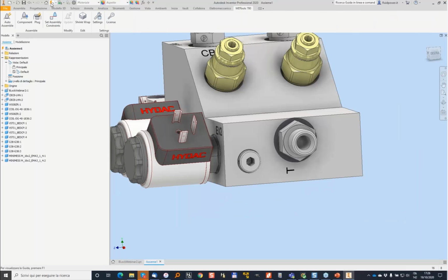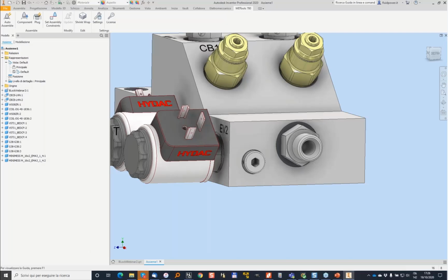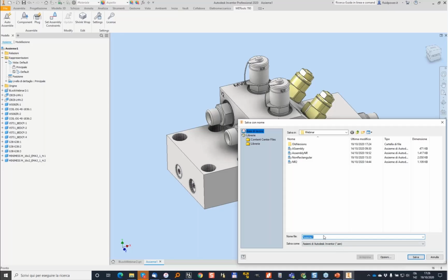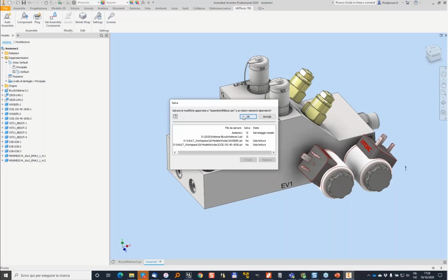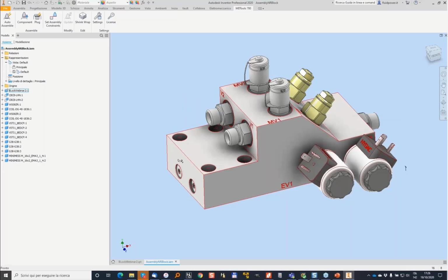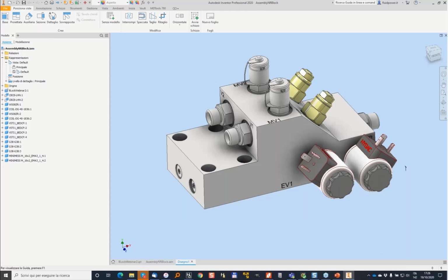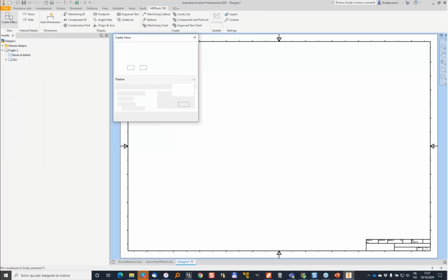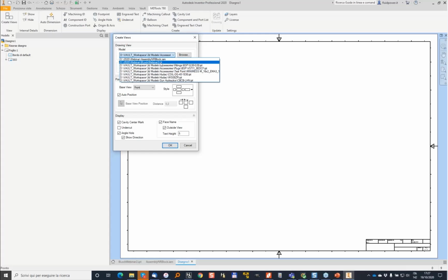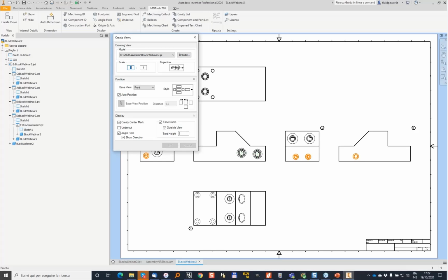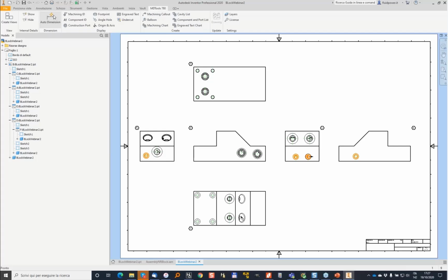We go back to the assembly and update the assembly, accept, and update with MDTools command. Our block is completed. We can go to the assembly. We can go to the machining drawing. Machining drawing works no different than a rectangular manifold. Simply, you create the views, the 6 views of the block with MDTools commands. You can put the dimensions.